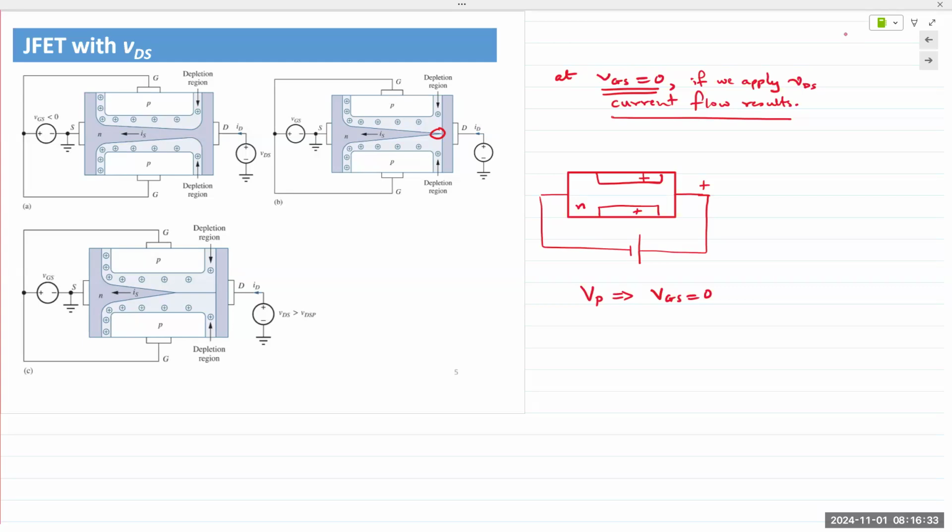We find forward current as from source to drain? Drain to source, IDS. Yeah. Forward, yes. So the question being asked is, which directions are we taking for the current and by extension for the voltages? So voltages are always measured as gate to source and drain to source. Current is also measured always as drain to source.